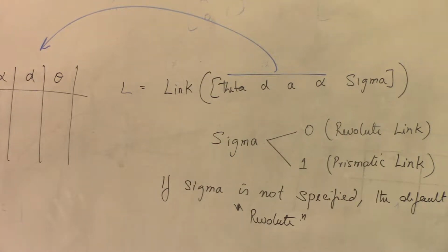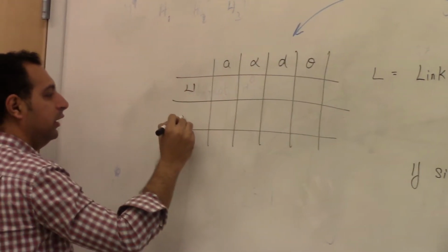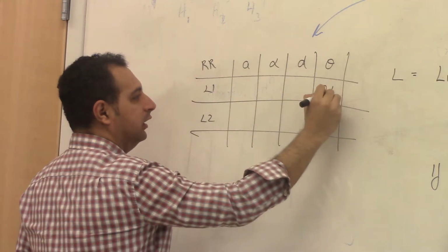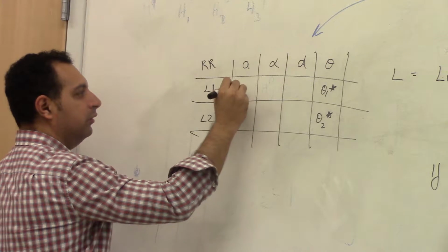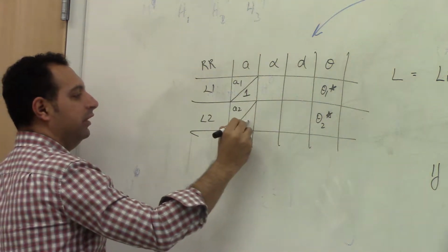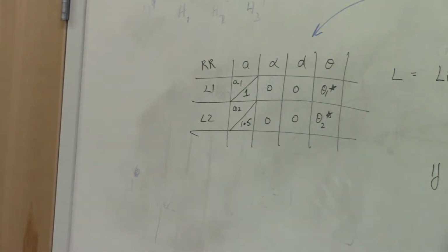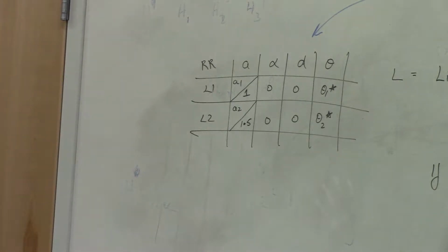Okay. So I'm going to give you an exercise sheet, and we will try to set this up. So let's say I have a simple 2 degree of freedom planar manipulator, right? So if I have a 2 degree of freedom planar manipulator, L1, L2, this is revolute. Usually for a 2 degree of freedom revolute manipulator, you will have theta 1, theta 2, these variables. All right, and this one will be A1, whatever the length is, A2. Now, obviously, we need to give it some values, so I'm just going to give this as 1. Let's give this as 1.5. Okay, this is 0, 0, 0, 0. We did this in class. Let's try to set this manipulator up and see how we can work with this. Okay, and then you'll see how to graphically analyze everything. All right, so let's go here.